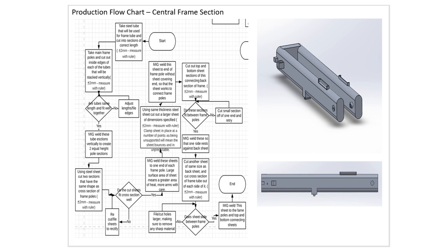There are good bits and bad bits about this. There's good bits in terms of the fact that we're seeing that there are tolerances popping up. Great. But the tolerances seem to be quite large. I mean, there's a 4mm tolerance, and this is a fairly large frame section component part, fine. But 4mm is quite a range of tolerance, given the fact that you're trying to get bolts and other bits in place. So are there issues with that in itself, and is 2mm for everything correct?